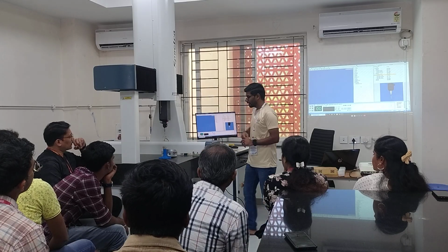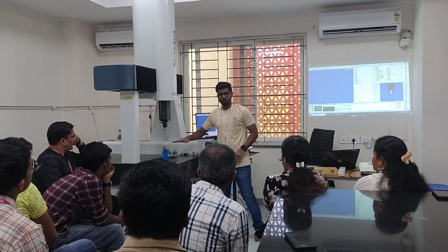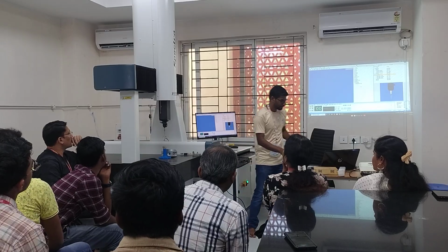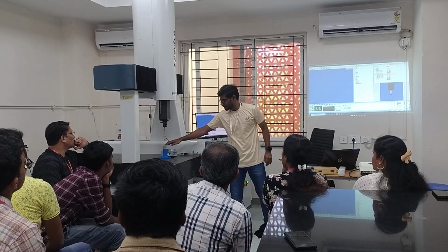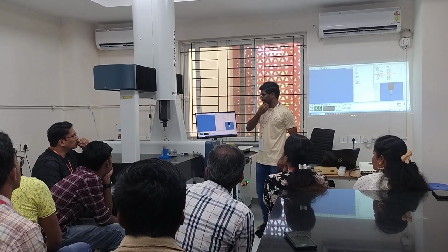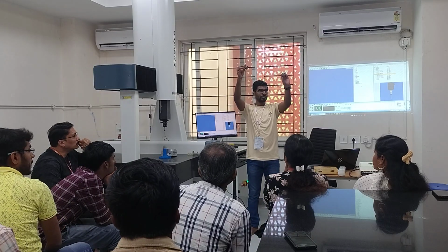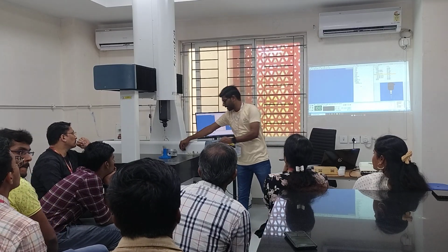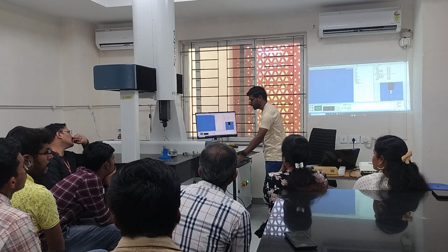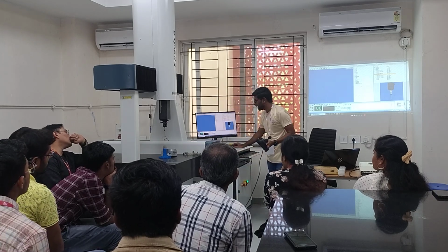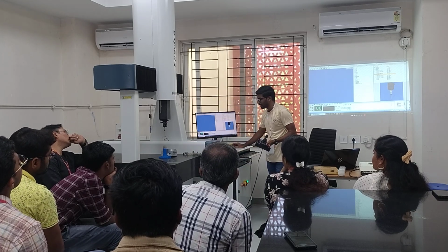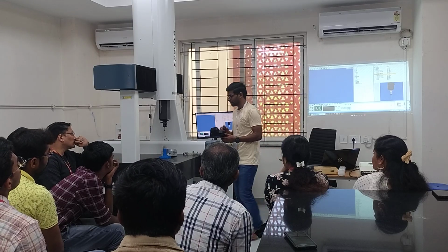Okay, so I'll start. On the top, it should be perfectly plane, isn't it? Because I have made this as a plane. This object, this model, is actually looking like this. So I will try to measure the top and find the planarity of it. I have to click on plane here and measure how many points. Let me measure 5 points.